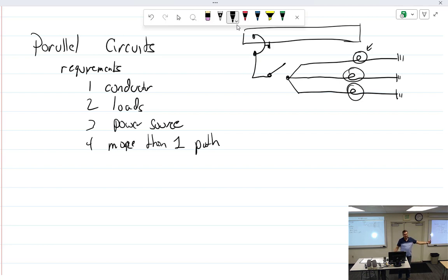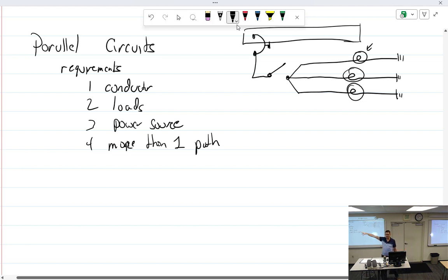So I have one wire that's going to run from the back of the instrument panel, right where that little switch is. It starts there, runs along the instrument panel, up the post, all the way out to the wing, right to the bulb, to the little fixture the bulb screws in. There's one wire right there. And then there'll be another wire that's usually soldered onto the casing of where the light bulb goes into. That's a wire about yay long that's going to go back and just screw right into the wing.